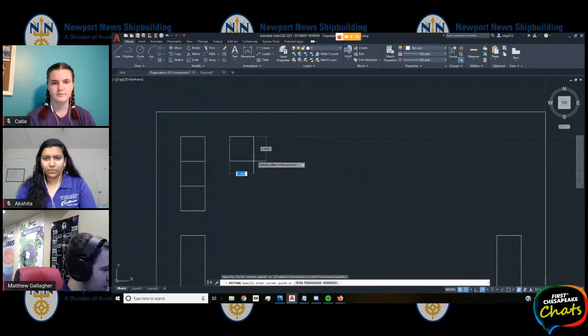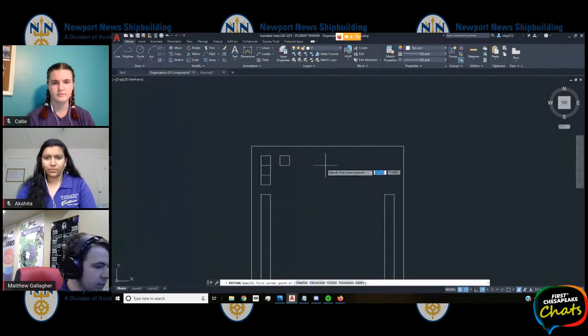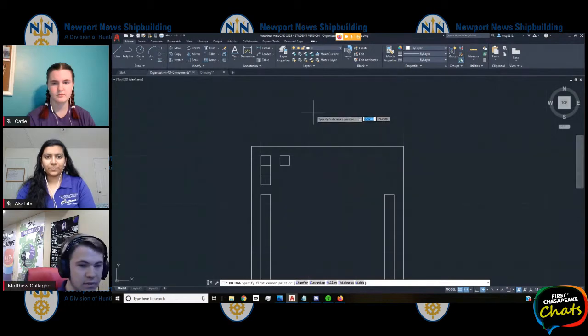We have our power. And you'll notice throughout this entire design that we only use one connection for power, even though typically for power and pretty much everything else, there's a positive and a ground or whatever you want to call it. But in 95% of the scenarios on a belly pan like this, the positive and the ground are going to be going to the exact same space. So there's no point in drawing 2 connections. Now, the only time you'll see this different is with the battery connecting to the PDP. And that's because we're typically going to have a main breaker separating one of those 2 connections.